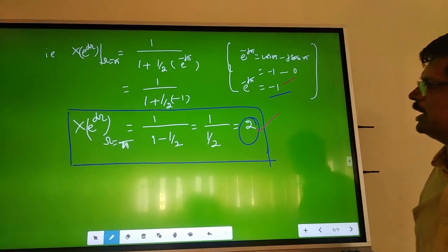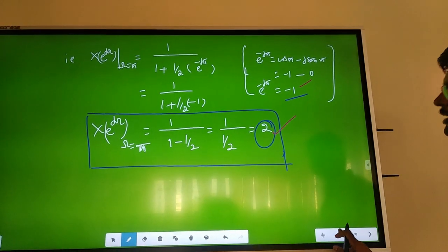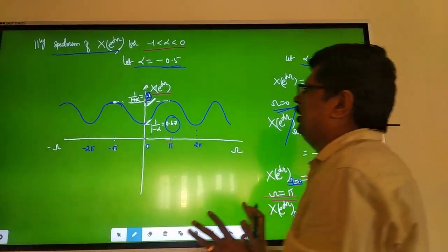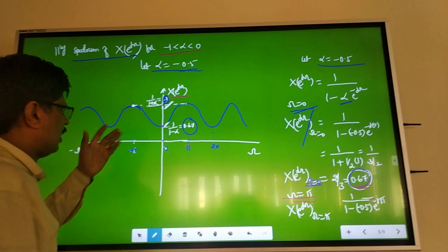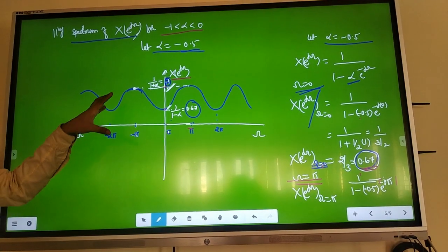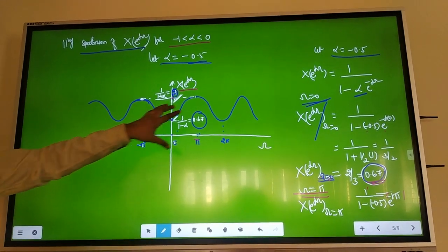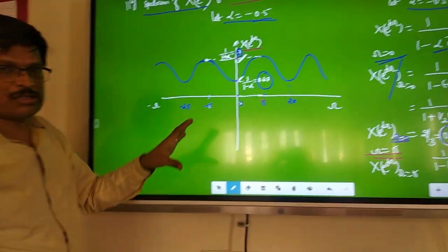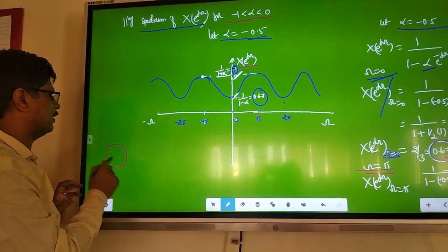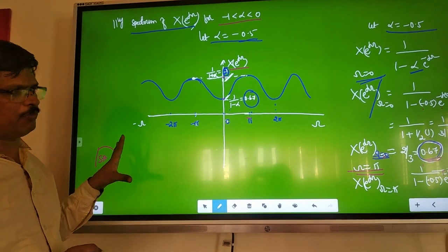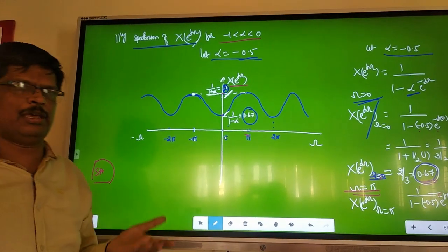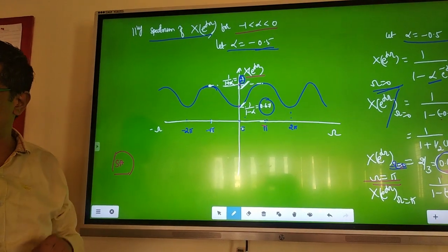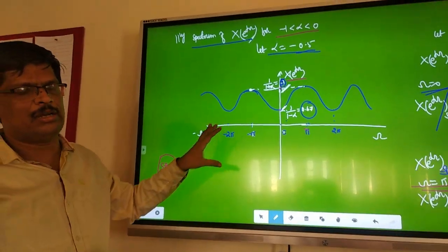Now this is how you will study. We can analyze the spectrum here. For this spectrum you can analyze the frequency, the energy, the power, the maximum, the bandwidth, and the distortions that occur, everything using a spectrum analyzer, right? That is useful information. Wherever the problem occurs in the channel, you can rectify and correct it.